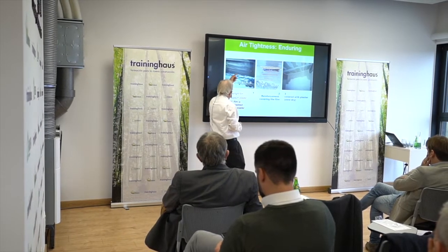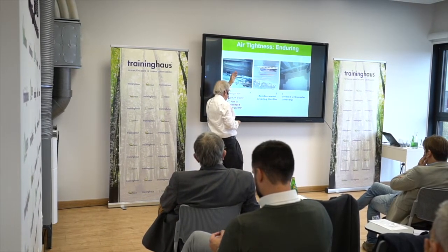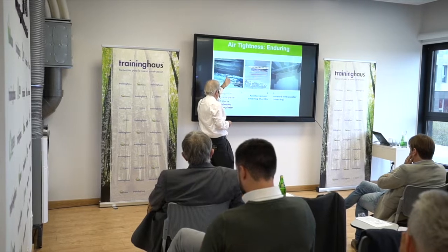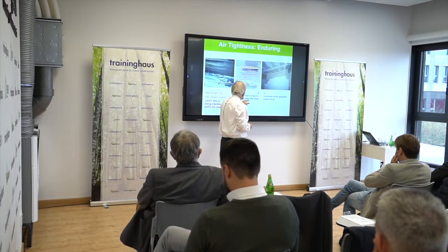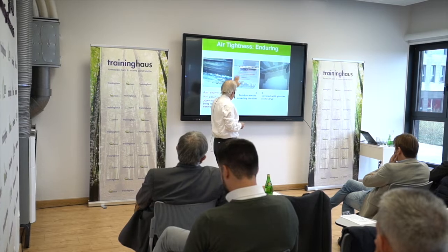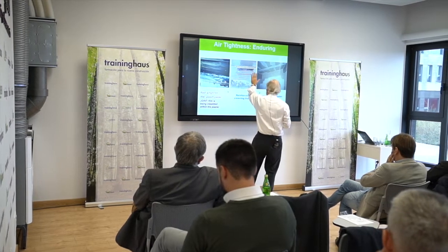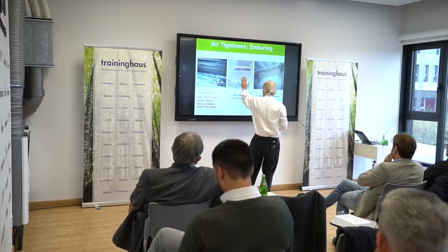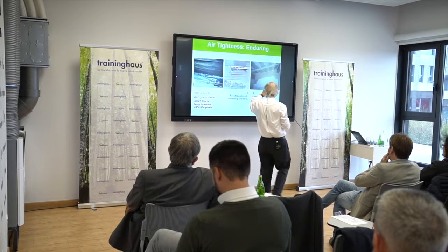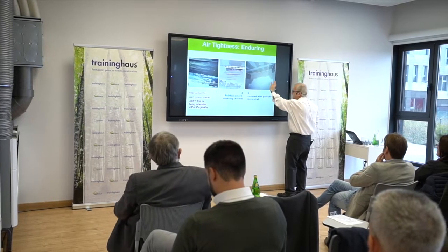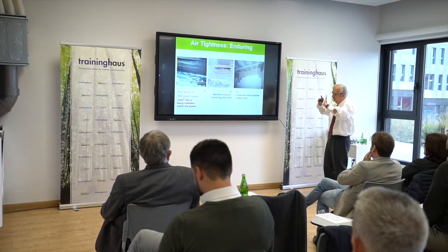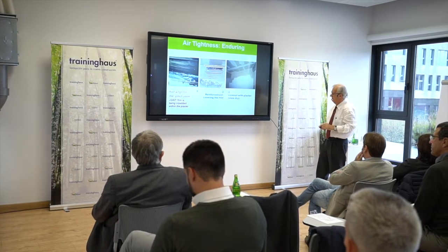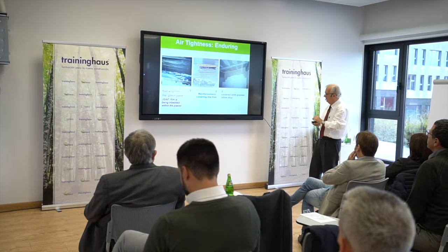So that would be the air retarder, vapor retarder on the inside, and then there will be this reinforcement covering the film. And the plaster is put upon the film, so the film is completely embedded in the plaster. And that's what you see here. Now it takes a little bit longer for the plaster to dry out, because in this case it cannot dry out to the external side. So that is how it has been done.